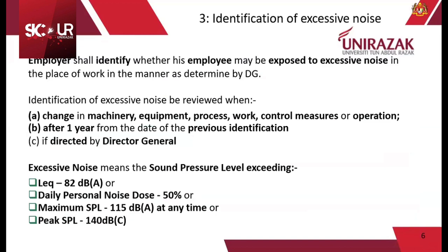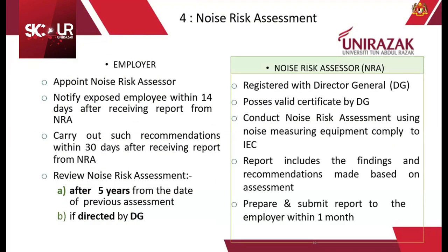Identification of the excessive noise to be reviewed when change of machinery, equipment, process, work control measure or operation, after 1 year from the date of the previous identification, or as directed by the Director General. Excessive noise means the sound level meter exceeding LEQ 82 dBA, daily personal noise dose 50%, maximum SPL 115 dBA at any time, or peak SPL 140 dBc. Right.